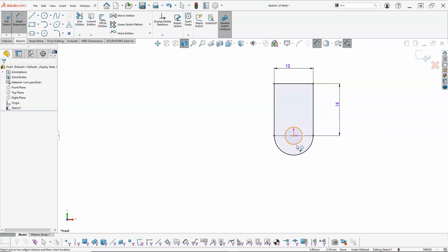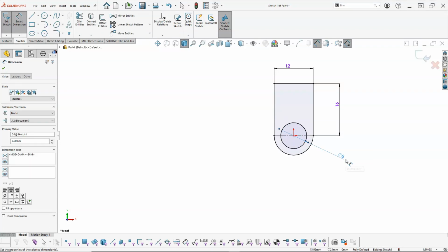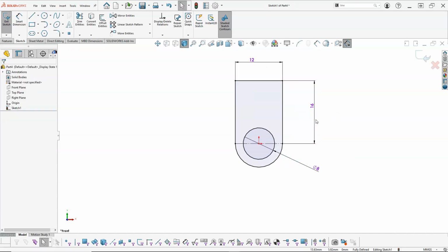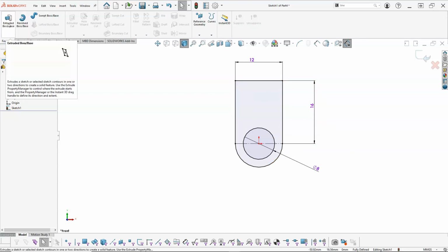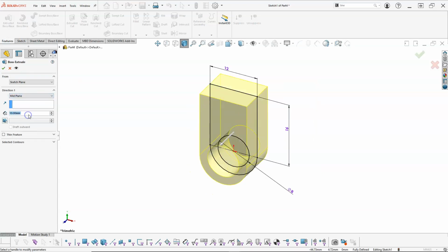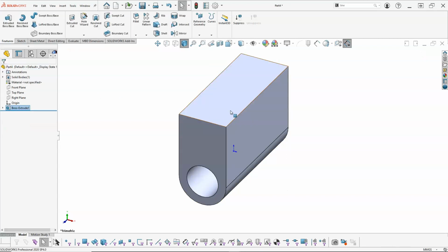Alright, so click at the center, drag out, place a dimension, we have our geometry. So by making that selection, that end face as seeing that as the geometry, we can get quite a ways in one sketch. Alright, so when I extrude this, I'm going to go ahead to the midplane, and we have a total of 30. And the advantage of doing midplane here is when I position the dowel pin hole, the driving hole, it should be over the origin. So we go ahead and accept.